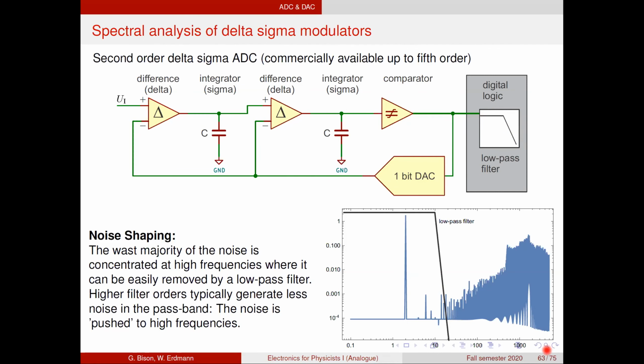Then of course we cut all the high frequencies with a very efficient digital filter. For that reason, those ADCs are pretty much immune to aliasing, because the aliasing signals would end up somewhere in these high frequencies, which are cut anyway by the filter in the digital logic.